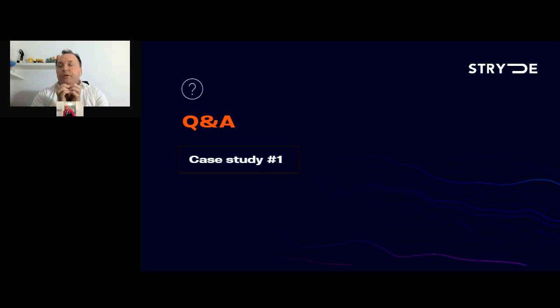Popping up is about GPS connectivity while burying the node. We have run tests with multiple customers in the MENA region. GPS signal can be achieved even at a depth of 75 centimeters below the sand. So that's something that is amazing. We have tried through testing. Obviously, we don't intend to bury the node 75 centimeters below the soil, but it could happen. Normally, burying the node 5 to 10 centimeters is a current practice.